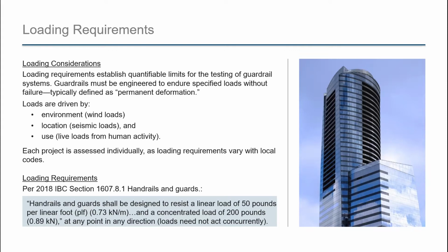Live loads or wind loads almost always determine the construction of railings. Seismic loads can occasionally affect design in high seismic regions such as California or some other areas around the country, but it's rare that it controls for railing design. Temperature loads are caused by expansion or contraction of the railing due to changes in the temperature. And that obviously occurs, we only consider that in exterior railings.